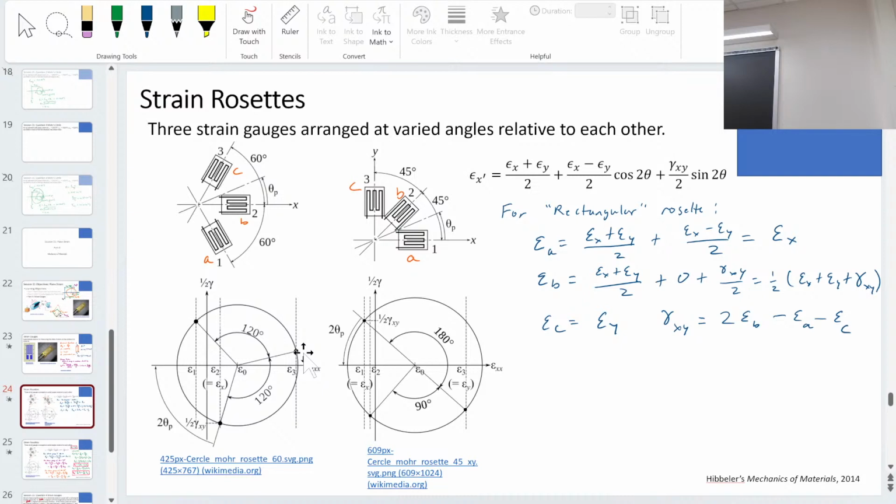If you take a cut going the other direction, then it's going to end up on the other side. These are going to end up going downward, the positive edge. But it depends on how you define x, because here it's defined as going outwards. This is the beam, this is the wall, so the edge is here. If I cut through here, then the positive shear will be going down, as long as I'm exposing that right side, and the normal force will be going out. Yes, that's right, that's this case.